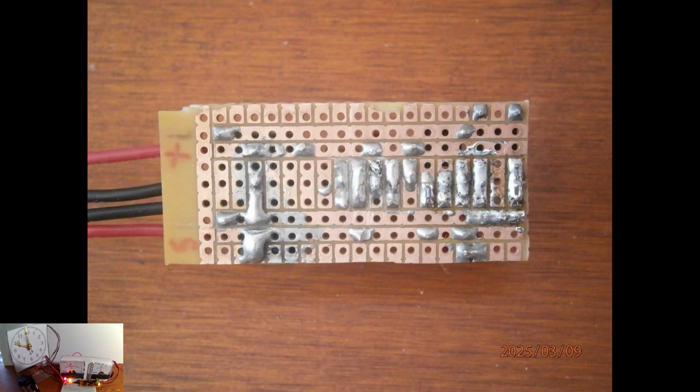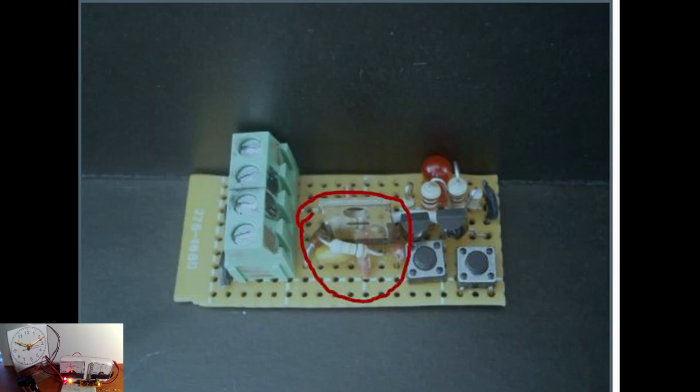5. Extreme care needs to be taken on printed circuit board layout and the quality of soldering, to reduce the possibility of parasitic capacitances, which may result in the capacitor draining faster than expected, resulting in the circuit staying on only for a few minutes. Believe me, it took me a while to have it working properly. Just look at my bad soldering job. Also, by having the capacitor C1, resistor R1, and diode D2 soldered very close to the MOSFET, the possibility of parasitic capacitances can be reduced.